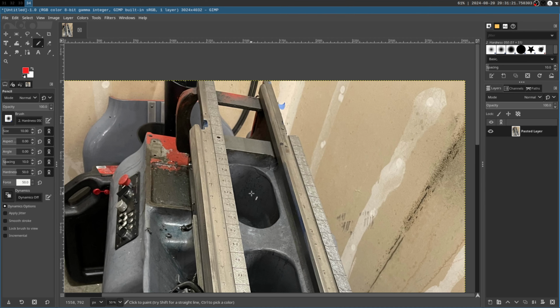So the scale that I'm working on building this lathe up to is affected by something like temperature. Different heat differences will affect the readings I get from day to day. So I'm trying to get the bed of this lathe ideally within 2 or 3 micron.